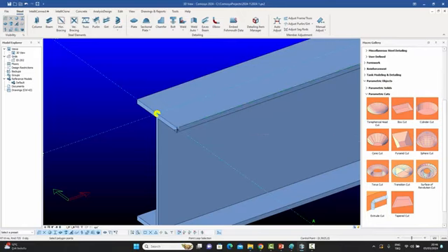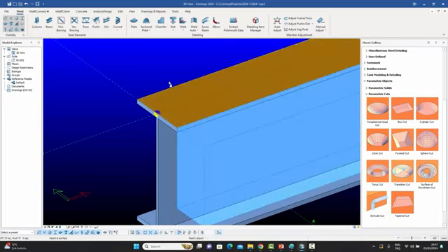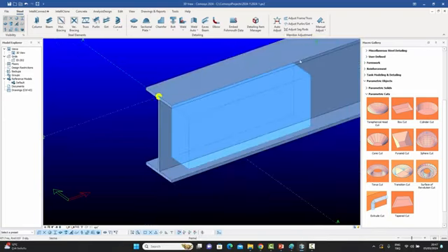Yeah, and then I can stick at this point and say dz minus 200. Oh, this feature is very useful. You can now select the last point again, and then it asks for creating holes inside this cut, which I don't want. So I'll just right click, and it creates that cut immediately over here.